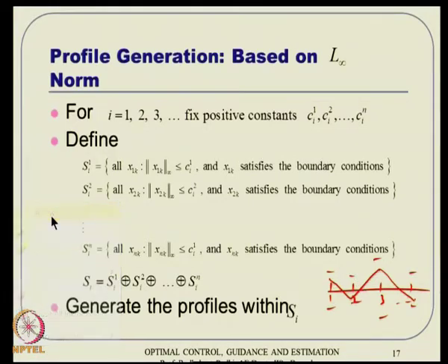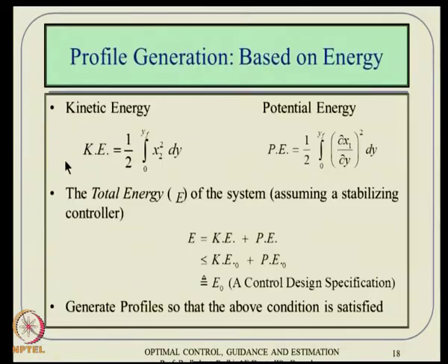Alright. So, the next idea is something energy based. Let us say you define kinetic energy as the integral from 0 to y_f of x2 squared, and the potential energy as the integral of (del x1 over del y) squared dy. Very naturally, this will come from distributed parameter system analysis.